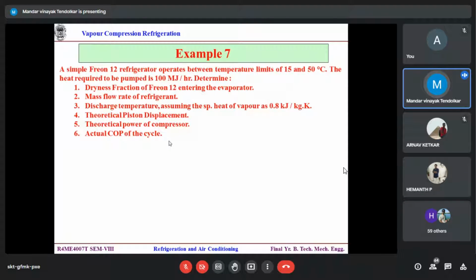I agree. So what should it be? Pump means what? Let's say a water pump. Water is to be pumped from a lower location to a higher location. So is it like the discharge part or the suction part? Now, unfortunately, or rather fortunately, water is incompressible, so pump work is very, very small over there. But what about gases? It will be larger. So is it a suction related part or the delivery related part? It's a gaseous compressor.